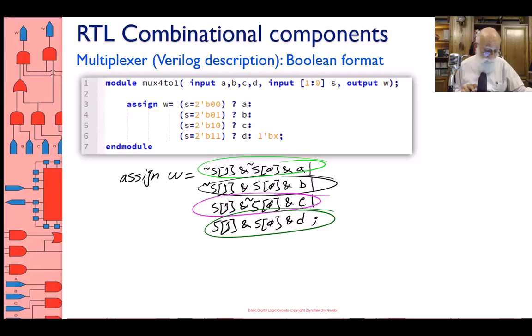All right, this is good with the multiplexers, and we have seen the Verilog, we have seen cascading, we have seen application. Application is this. For example, if you have several sources and you want to select one of those sources to go on your bus to go into some other system, so you put multiplexers there.